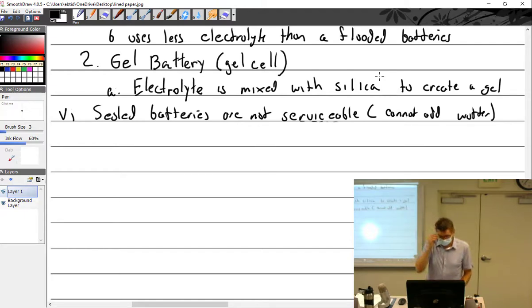So, all right. Basically, you're just saying get a new battery. Legally. No, charge it, service it. Is that why? Let's say you're in flight and your alternator's doing all the legwork, but then your engine dies, then you lose all your communications basically. Yeah, you would. Right about the time you really need to communicate with somebody and say Mayday, Mayday, Mayday, you just lost the alternator, you had no battery, so your radios are shut down, and you're like, wow, this just really turned from really bad to really, really bad.